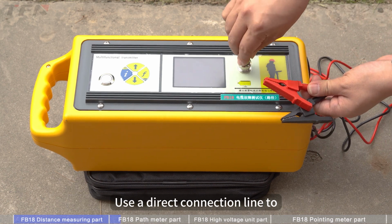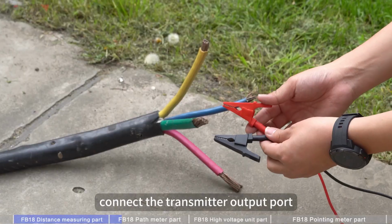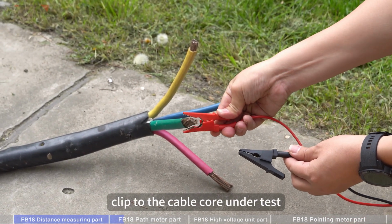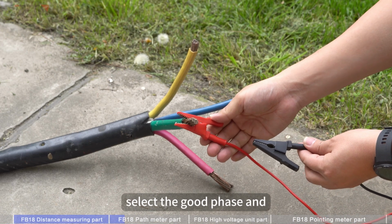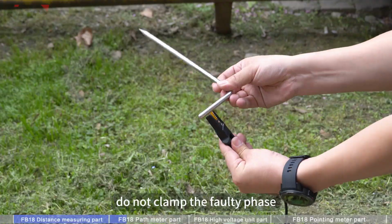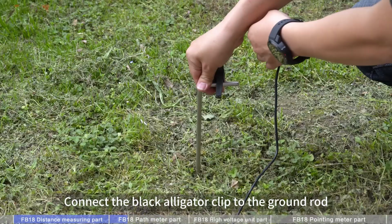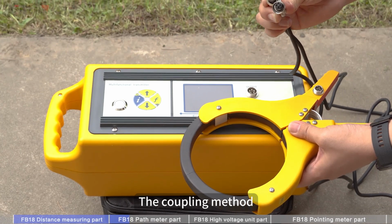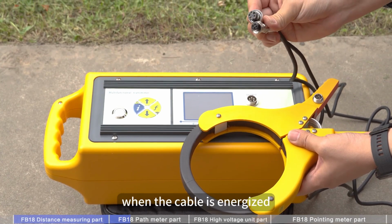Use the direct connection line to connect the transmitter output port. Connect the red alligator clip to the cable core under test. In the pathfinding mode, select the good phase and do not clamp the faulty phase. Connect the black alligator clip to the ground rod and insert the ground rod into the soil. The coupling method can realize pathfinding when the cable is energized.